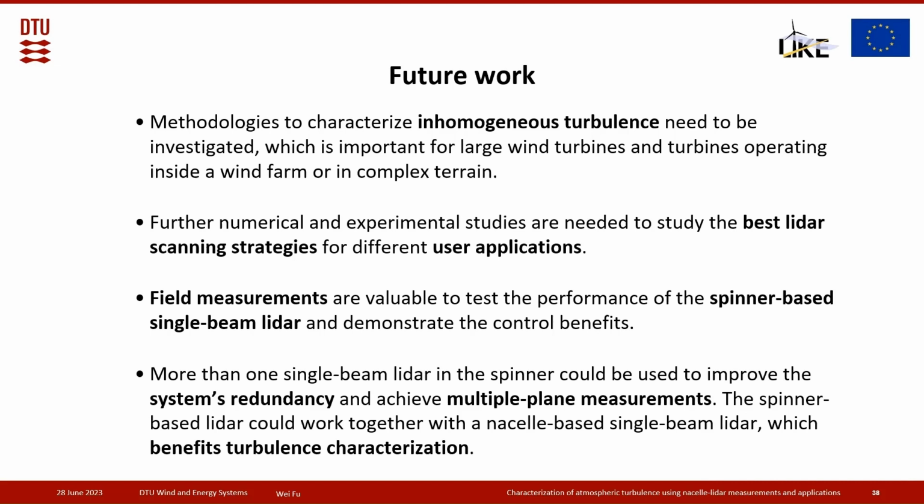Lastly, more than one single-beam LiDAR in the spinner could be used to improve the system redundancy in case one of them is not working, and to achieve a multi-plane measurement, which could improve our wind preview quality. Spinner-based LiDAR could also work together with a nacelle-based LiDAR. So one steering beam in the middle and a circular pattern, and they could combine together, which also benefits turbulence characterization.